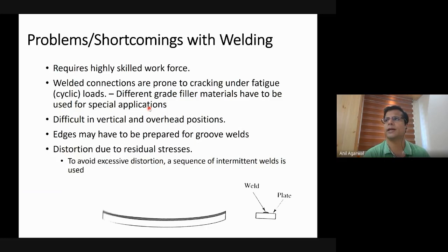For groove welds, you have to do the edge preparation, which you can compare with the drilling of holes in bolting. So there may be extra cost and extra machining involved if you are going for a groove weld, but if you're going for a fillet weld, that's not a disadvantage, that's not a problem. You don't have to do much edge preparation.